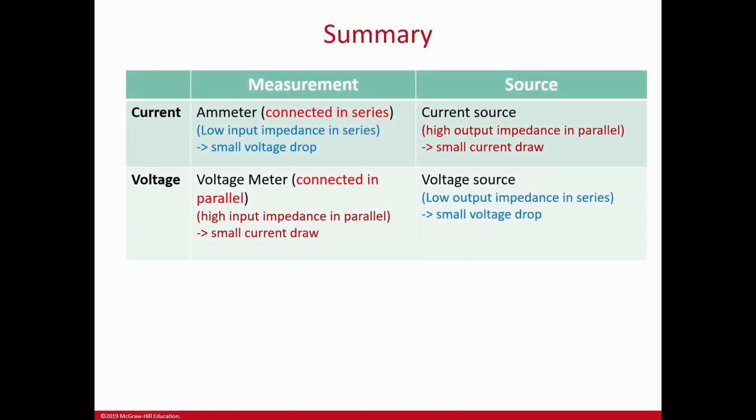Just to remind you again, because there is an output impedance connected in series, in order to have a small voltage drop the output impedance must be very small. This is very similar to the ammeter, because an ammeter is also connected in series, so its input impedance is very small.